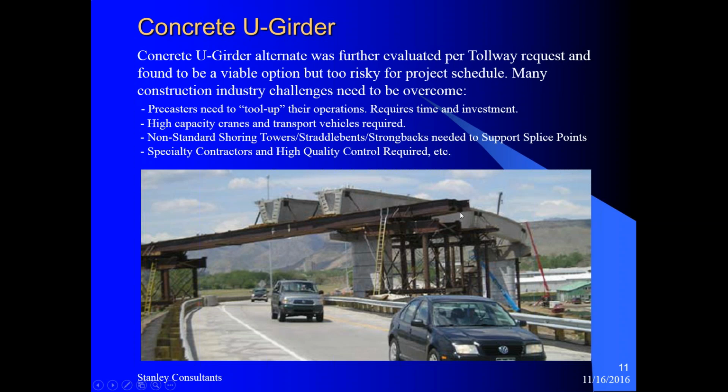In addition to that, due to the weight of these sections, new high-capacity cranes and transport vehicles are required, and non-standard shoring towers with straddle bents, trunk pegs are needed to support the splice points, because these girders come in pieces and they are spliced in the field.